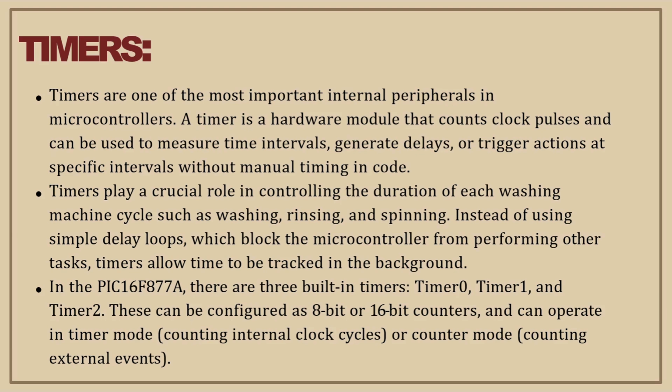These can be configured as 8-bit or 16-bit counters and can operate in timer mode, counting internal clock cycles, or counter mode, counting external events.